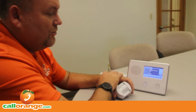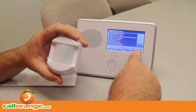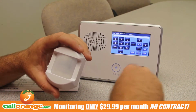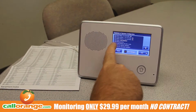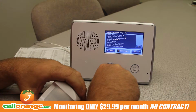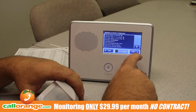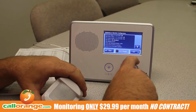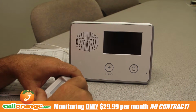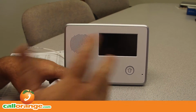It's that simple. When you're done, the last thing you're going to do for it to actually program in the panel is, when you're done your last sensor, you hit skip, end, and then it brings you here. Okay? This check has to be on, save changes, okay? Otherwise everything you did, you got to do again. So make sure that yellow check is in there, yellow orange, and then hit exit. It's going to shut off, turn back on, and all your changes have been made. Everything's saved in there.